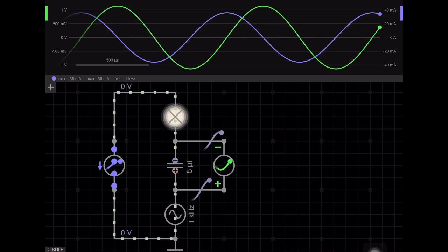But in the RC phasor diagram, you might have observed a phase angle phi less than 90 degrees. The reason is that there we are taking the resultant voltage and the current. The resultant voltage and the current won't have exactly 90 degrees. Why? Because there is a resistor component there. If there is no resistive component, the current and the resultant voltage will have 90 degrees. Why?